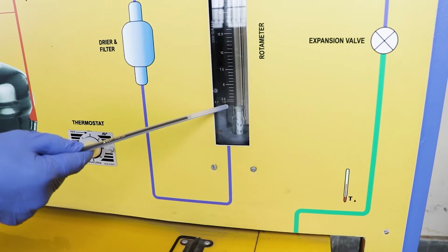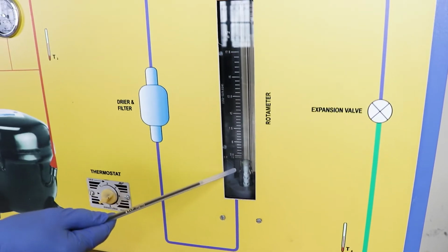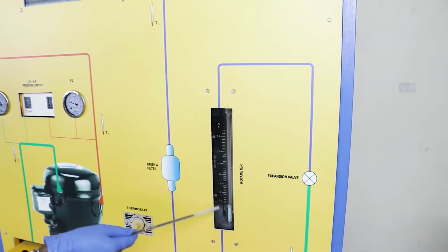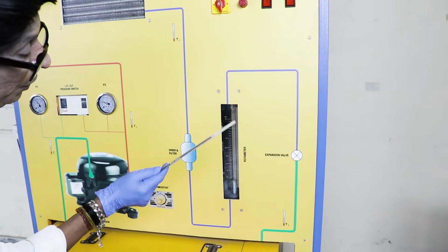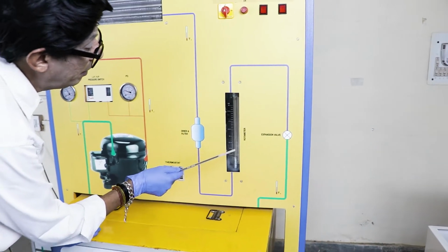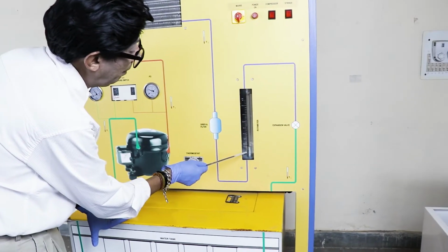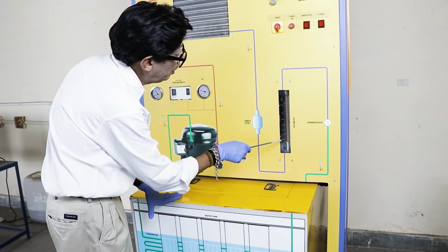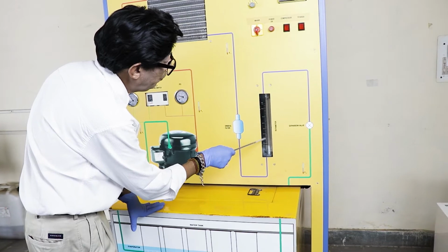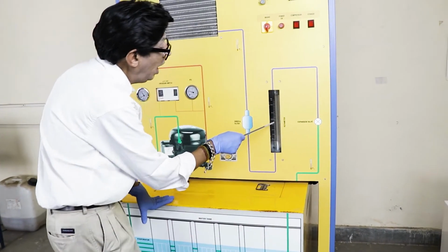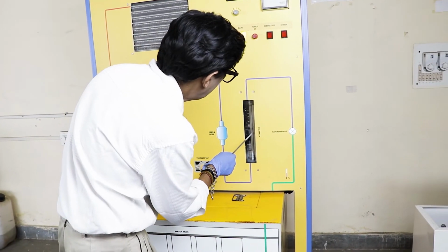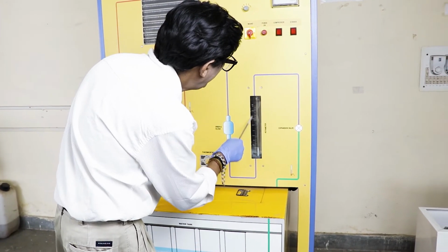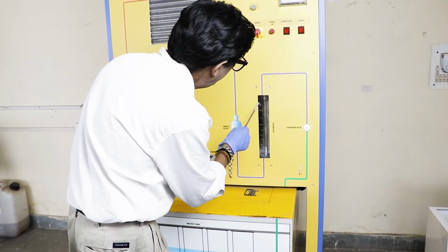When the refrigerant flows from the bottom to the upward side, this float lifts, and the lift of this float is proportionate to the flow. We will start and show you the lift of this. This lift of the float is used as a measurement of the flow, because the flow will apply a force onto the float, and there will be a gravity force in the opposite direction. So the float will remain stationary somewhere, and wherever it becomes stationary, we read it from the scale. There is a scale over here which is graduated in liters per hour. The unit is liters per hour.